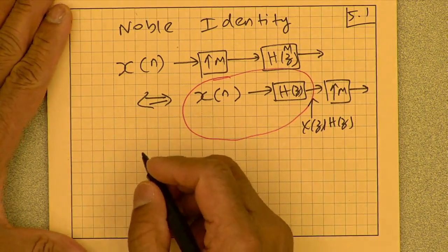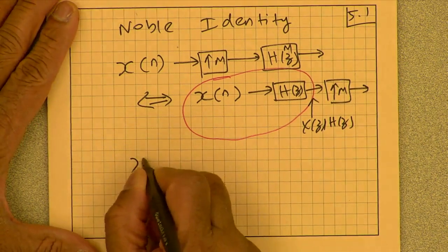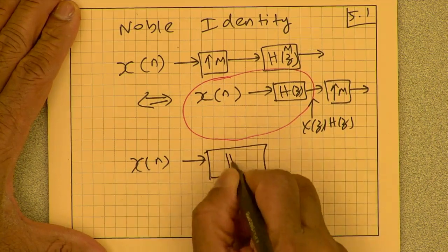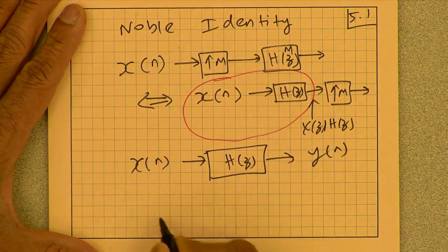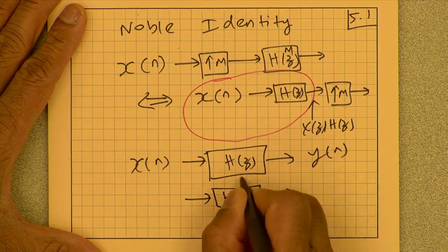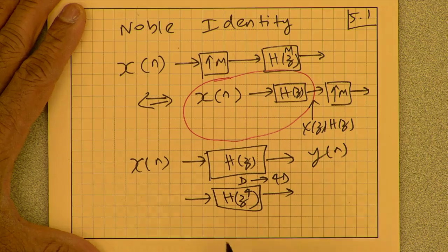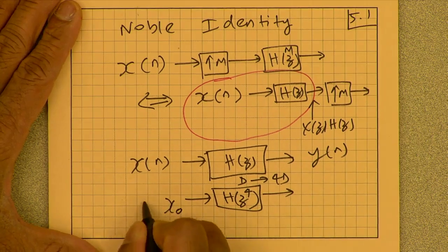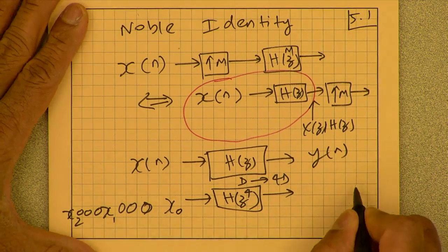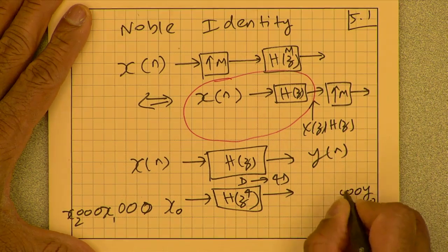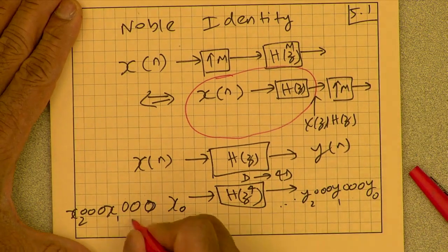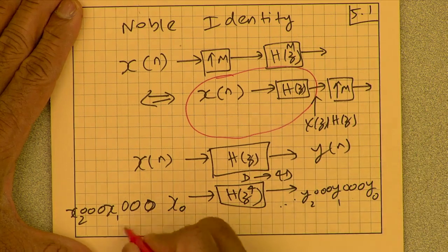In any case, the idea of interleaving. If I have x[n] going through a filter H(z), and we are computing y[n], and I replace every delay D by 4D, wherever you have one delay, then we take x0, 0, 0, 0, x1, 0, 0, 0, x2, etc. And we will now be able to compute y0, 0, 0, 0, y1, 0, 0, 0, y2, etc. These are computed correctly, but the zeros are null operations.